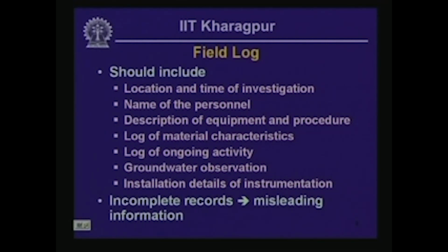It is extremely important to have a very complete record of whatever is going on during the subsurface investigation, because the investigator's report is the only thing that gives the designer of a particular facility the details of what happened during the investigation, and if the records are incomplete, then the inference that the designer draws from the field record is going to be insufficient and often misleading.